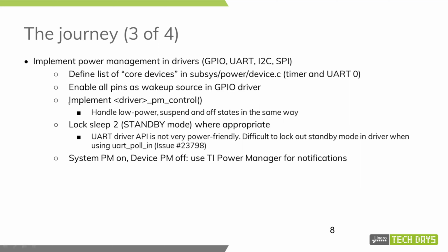And then I implemented a PM control function in each driver to handle the low power, suspend, and off states. I handle them all in the same way because these devices only have on-off state. And then I had to lock out the standby mode whenever there is an ongoing transfer in these drivers.